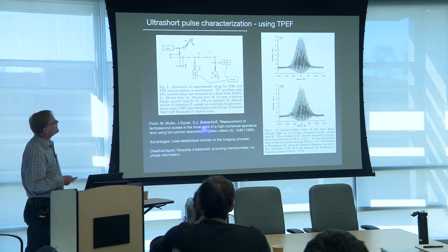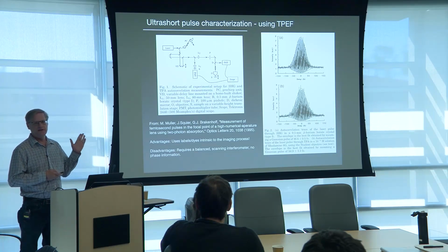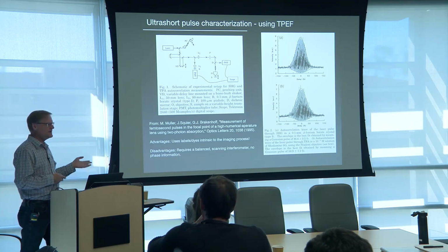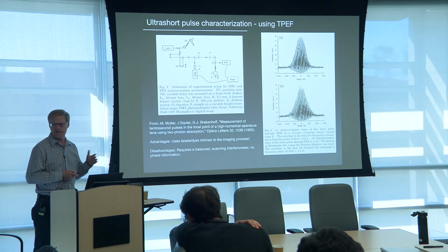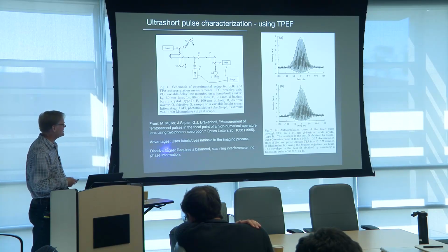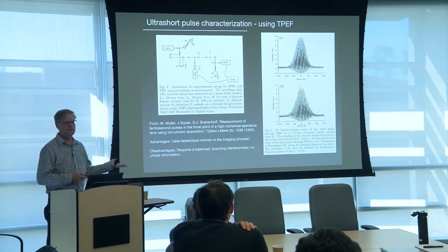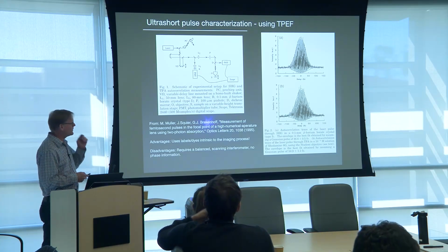Okay, the disadvantage in my opinion is this guy. It can be a real pain to implement, and you got to pass through the pulse width. So that if you're using 100 femtoseconds, that's 30 microns. That means you got to have these guys matched within less than 15 microns. So it's a little bit of a pain to build this guy. And then finally, there's no phase information of your pulse in this kind of a system. But you do it at the full NA.